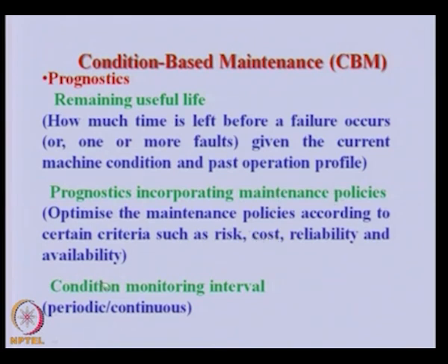Then third is the condition monitoring intervals, periodic or continuous. Depending upon the type of machine and criticality of the machine, we can decide whether a particular machine requires periodic monitoring or continuous monitoring.